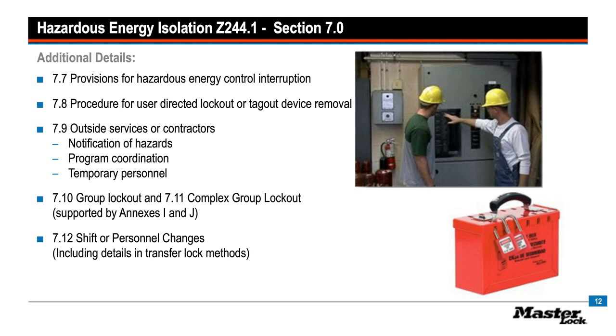There are any number of accidents recently documented that show that temporary workers who did not receive proper initiation into the hazards of the work floor often got jobs that were at a minimum setting them up as affected personnel, and in some cases in situations where they should have been authorized to apply lockout and have not.